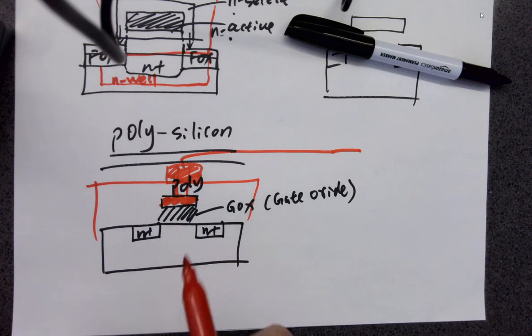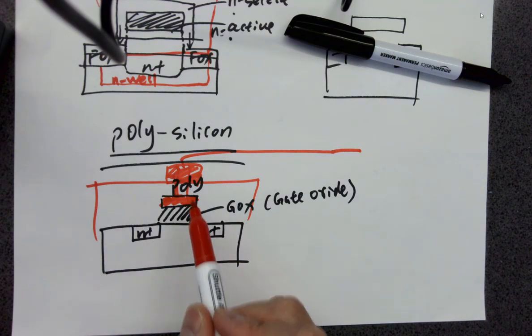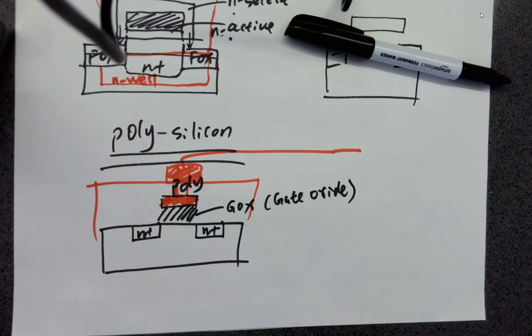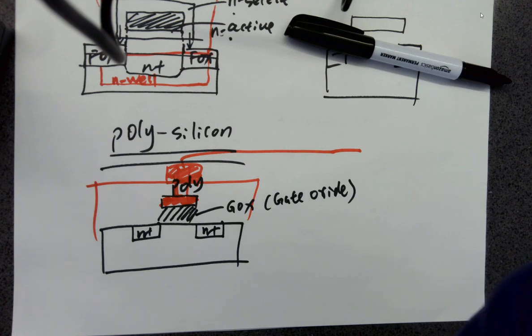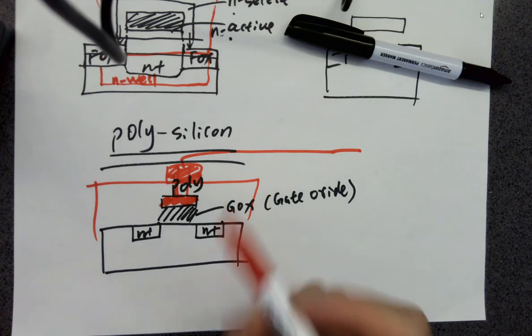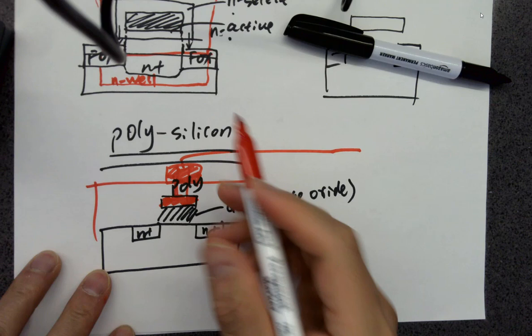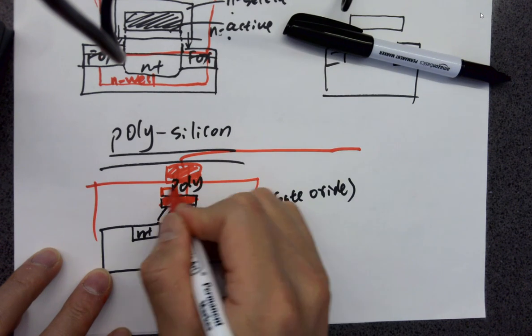Okay, there is one way you can use polysilicon for relatively longer distances, but the only way to do that is to go through a certain process, and we are not going to do that for this class, because there's no fabrication for this class. So you have to specify that with the manufacturer. You want to tell them you need a certain layer on the top of the poly. So let's draw it here like this.